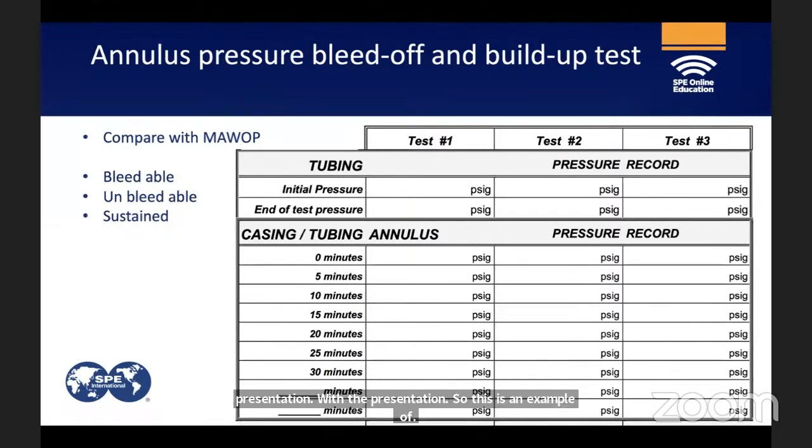I could not share with you the plot, but the y-axis could be the pressure and the x-axis could be time. You can plot all the pressures for the A annulus, B annulus, and the tubing. If it is a dual completion, you can plot two tubing pressures, and then you can see with time how they are changing. Also, you can plot the temperature. If you have a downhole gauge for pressure and temperature, that is an added advantage for diagnostics, just to see the correlation.